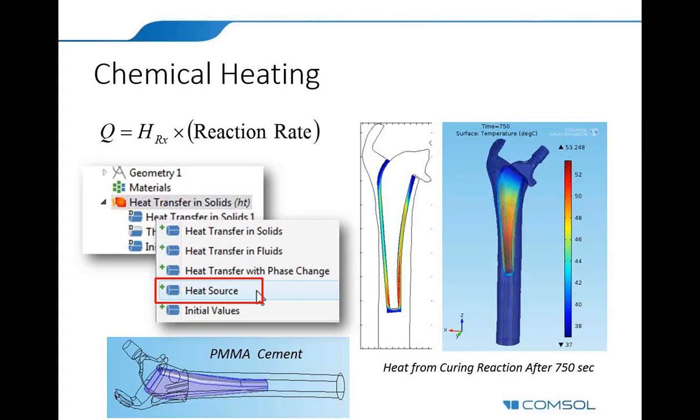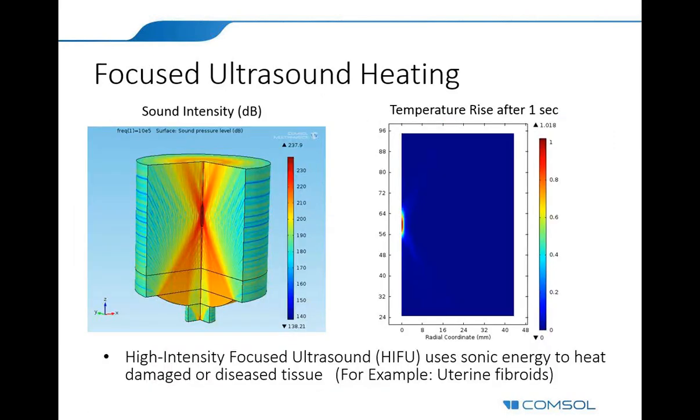Well, the problem that you run into, of course, is that the curing of that PMMA cement is an exothermic process, and bone is a wonderful insulator. So you could find that it gets too hot, and you actually could start having tissue necrosis in the bone, which of course would be a disaster. So we could do that.